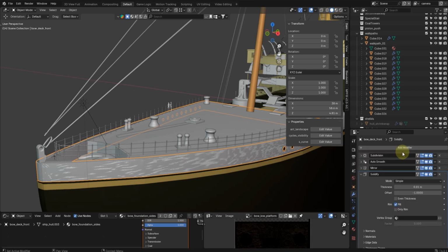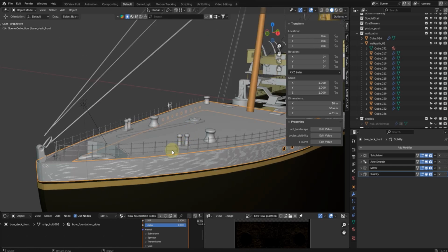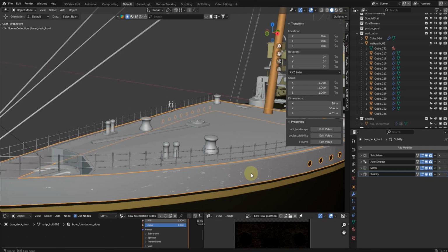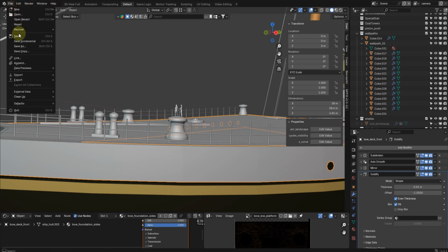And this time you observe a few things in terms of how we export FBX, either apply transform or not apply transform. So it looks that way because the surfaces are too close. When you move closer, it seems to clear out, but I'll probably make a modification to this solidify modifier and make it even thickness, and probably increase the thickness as well, and then do an export.